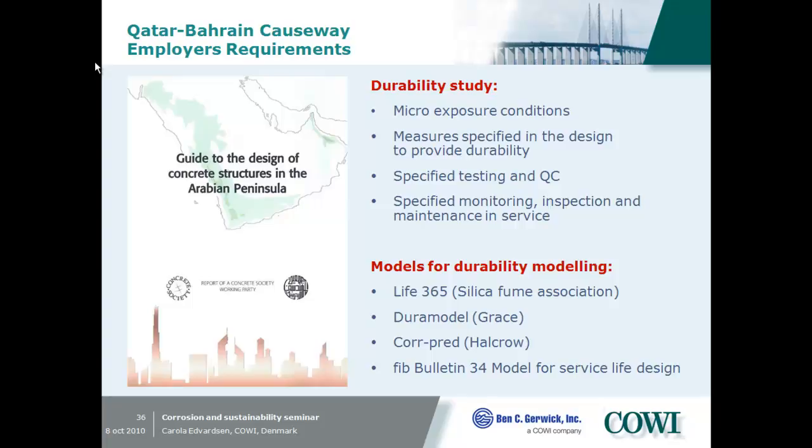As we said and discussed yesterday, in our part of the world, it's not used. We do not recommend using corrosion inhibitors and so on. We are very skeptical about the long-term performance. And it must be possible to design a concrete structure without using microsilica or corrosion inhibitors. And the other thing is you have to put these inhibitors in the bulk of the concrete, and you only need it at the concrete cover. So by using so much money for the bulk of the concrete, we should rather concentrate on making a good cover concrete.